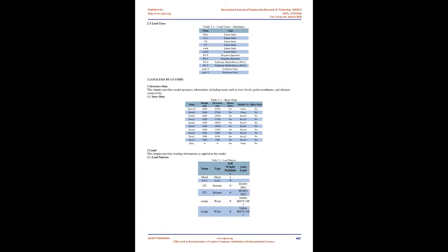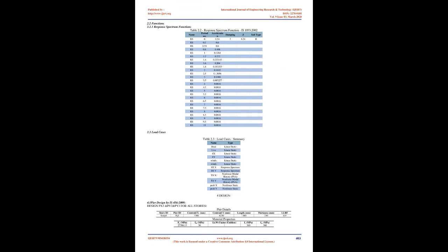Pradeep Pujar, 2017. Analyzed G plus 9-storied irregular buildings to find their seismic performance with and without shear walls. Shapes of building plan considered for the study were I, L and C, 3 models of bare frame and 3 models with shear walls were considered for the study. The models have been analyzed by equivalent static technique with the assistance of ETABS v15.0.0 programming. The comparison has been done by considering the parameters such as story displacement, story drift and base shear.